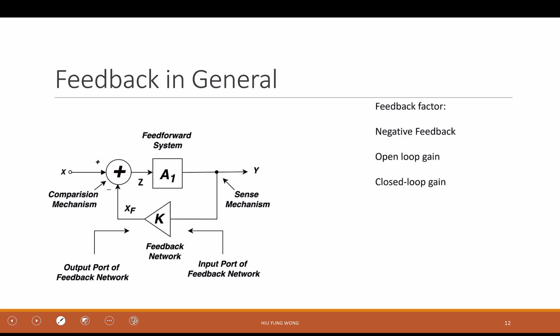And then do a comparison. Again, you cannot do subtraction as in digital signal processing. You can do subtraction, right? So this part will be an analog circuit, usually. And very tiny. You don't want it to overwhelm the feed-forward system, right? Because it's going to take a lot of energy and area. So we have 4 parts: feed-forward, sensing, feedback, and comparison.